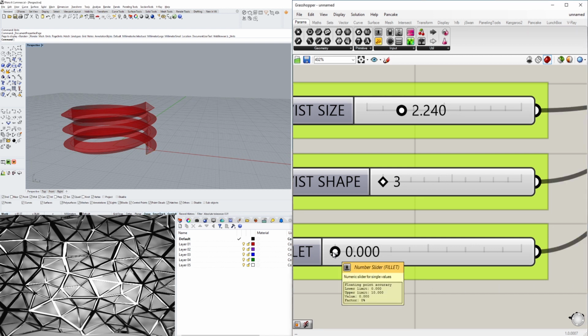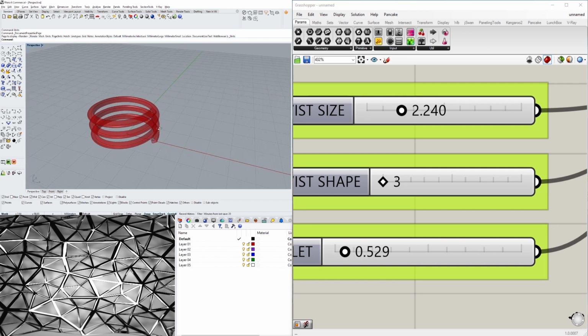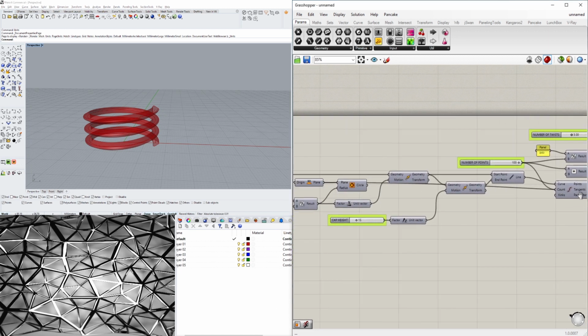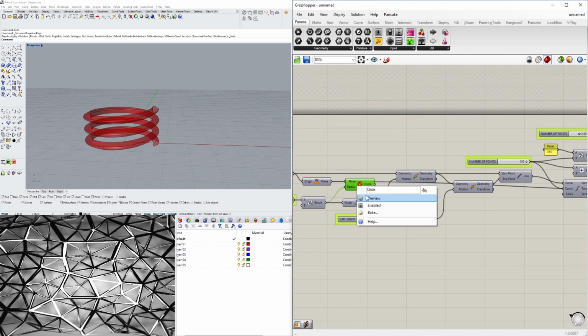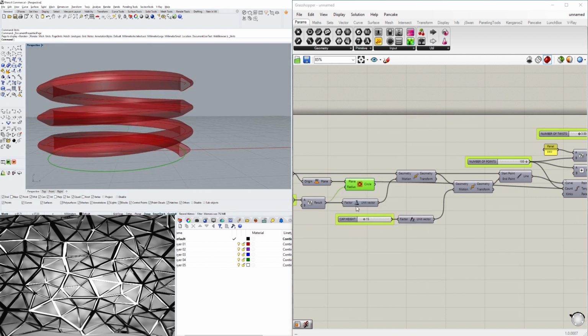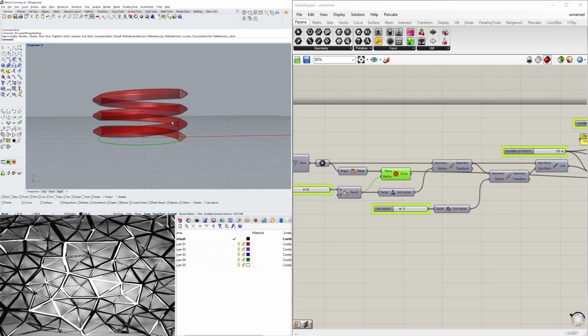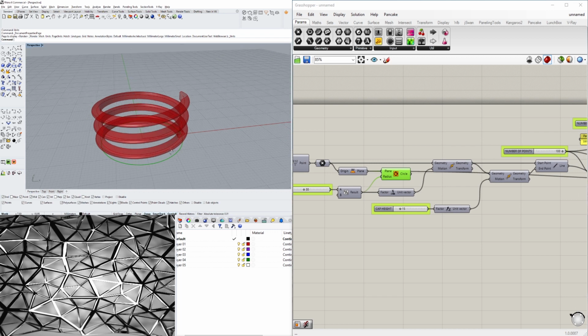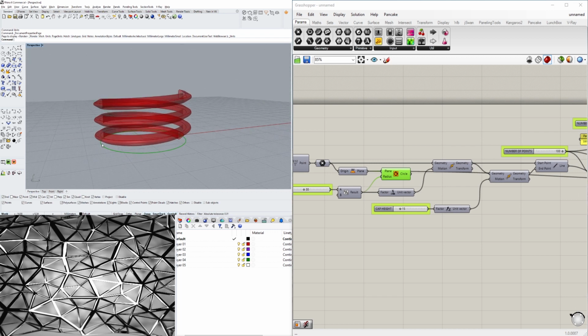So for this next part, I'll keep it a little bit simple in the sense that we'll just take this and we'll join this with a form to create kind of the inside portion of the cap. So let's go here to our initial geometry, which is our circle. Now, we actually haven't used our circle at all, and it was one of the first things that we did, but that gives us an idea of kind of the location and the size of our cap. Now what I'll do is I'll actually just extrude this up to create a solid.